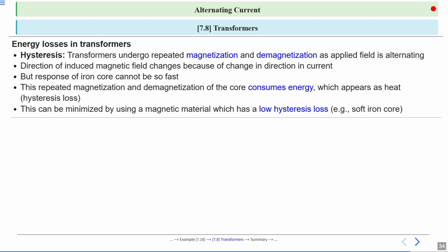So what were eddy currents? Eddy currents were circulating currents induced in the bulk of a conductor or on its surface, like a sheet of conductor or a solid structure of conductor, not a wire. They are loops of currents, induced due to change in magnetic flux through that conductor. We break the path of eddy currents by using laminated sheets, due to which eddy current loss is decreased.